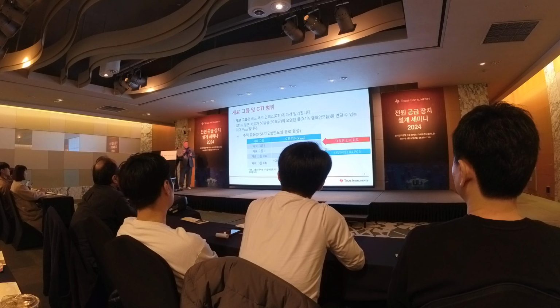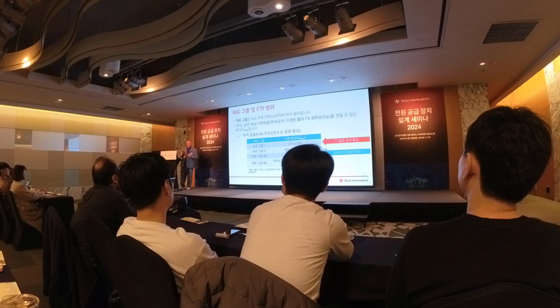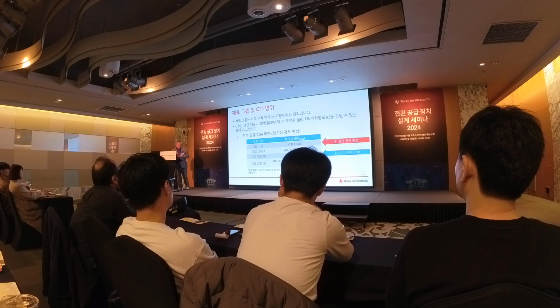Material group 2 is between 400 and 600 volts. Material group 3A is between 175 and 400 volts. Material group 3A is important because this is generally the material that PCBs are made out of. So standard FR4 material for PCBs is material group 3A.